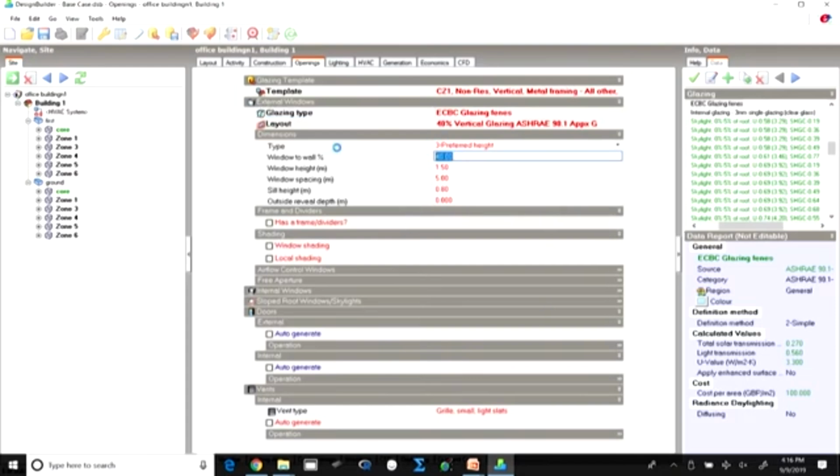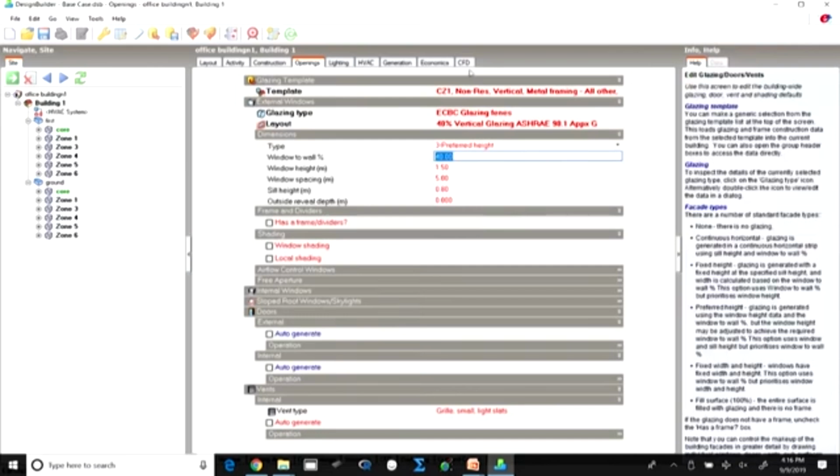So, what we have done so far is we have taken all the prescriptions as per ECBC and given all these values as an input into this building which we are currently examining, and this is the base case. Just to remind you over and again, for the base case, we will take all the prescriptive values as given in ECBC and put them in the input parameters.